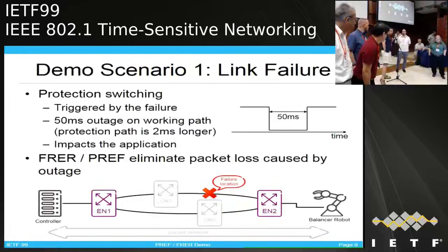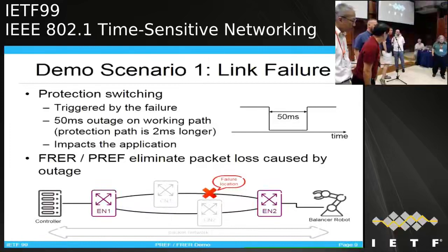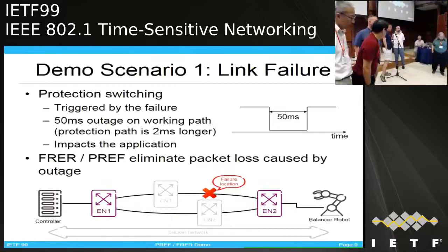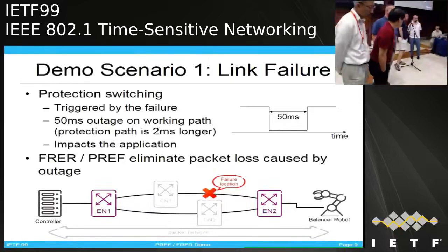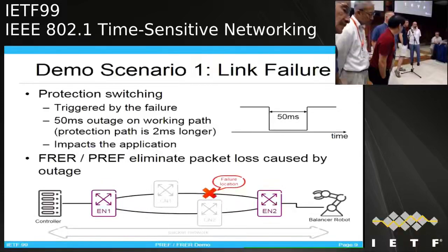If I may add, it may be unusual to the IETF, but it's a very classical metric for the applications in industrial control loops. The number of losses in a row is very critical. Usually they will always let you lose a packet, but if you lose 3-4 packets in a row, they will stop the production line. If they have to stop the production line like twice in a year, your hardware is on the curb.